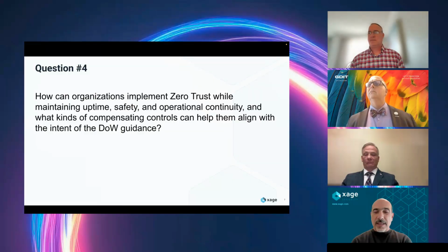That does not mean, though, that some of these controls cannot be implemented, right? For example, the guidance calls out for MFA within the OT environment. Well, most PLCs don't support MFA, and they won't for a very, very long time. But it doesn't mean that PLC will have to be decommissioned. MFA can be today delivered as an overlay compensating control on top of the interaction.